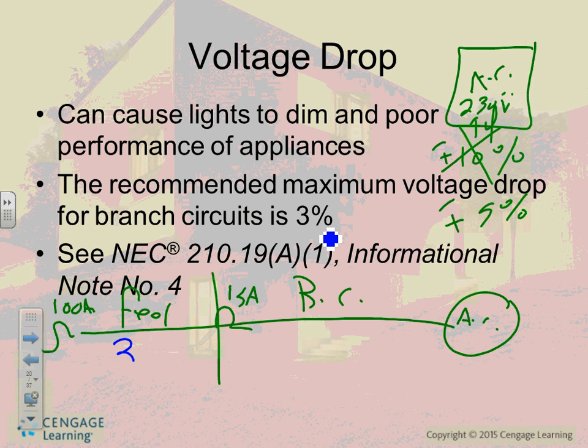Here's the component you can do, John. Number 1, 3%, typically, here's what the engineers do. 3% drop on the feeders, 2% on the branch circuits. For a total of what? 5%. Does that make sense, guys? 2%, 3%. Why would you do 3% on feeders? Anybody? Why not the other way around? Yes, feeders tend to travel further. Now, does the NEC code book care, guys, if you put the 2% on the feeders? No. But we always give 3% on feeders and 2% on branch circuits.